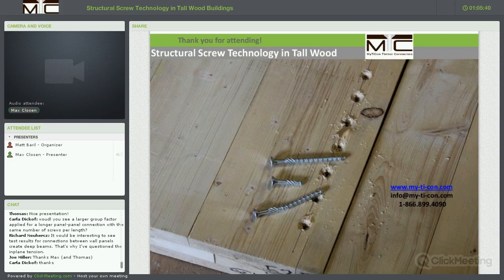We would have to check into this and see if there is test data or a research paper available to estimate something like this. However, if you are looking at this, you can derive capacities and stiffnesses out of the theoretical approaches that already exist. We can calculate the withdrawal resistance in a CLT panel fairly accurately on the conservative end with the design methods that we right now have. And if we fasten a CLT panel to a CLT beam, building a T section, we could potentially use the mechanically jointed beam theory, which we introduced in one of our papers late in 2014, to design these connections and estimate the stiffness of the connection system. So if you're interested in looking at this, we can definitely hook you up with the right data on this and propose an approach for you.